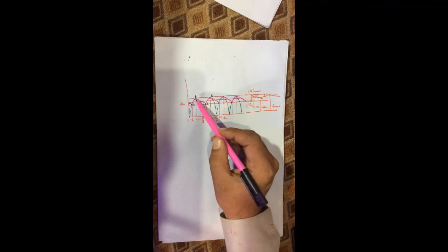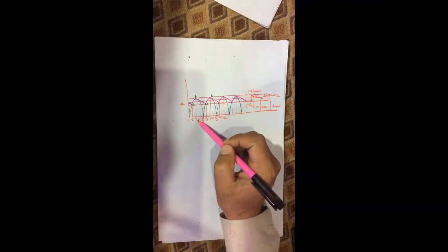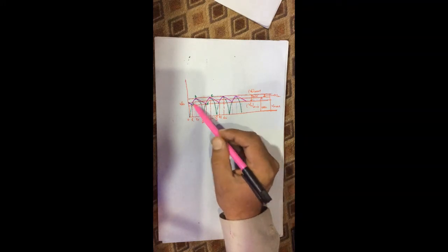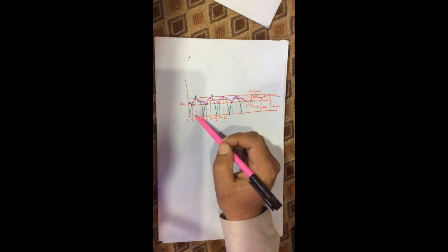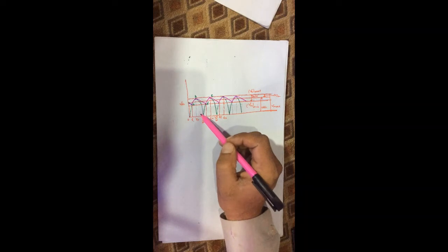Now the plate carrying positive charge of the capacitor is connected to the inside of the diode D1, so it will reverse bias the diode D1 at time t equal to t2. At the same time, diode D2 is already reverse biased, because this is the first positive half cycle. In the first positive half cycle, D1 is forward biased and D2 is reverse biased. But beyond this point, the diode D1 also becomes reverse biased. Now the capacitor gets discharged.